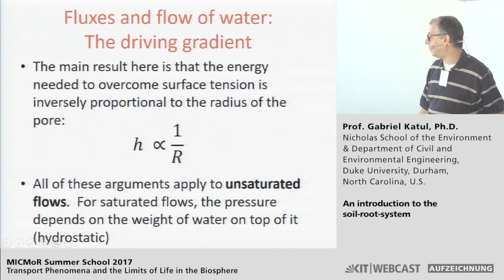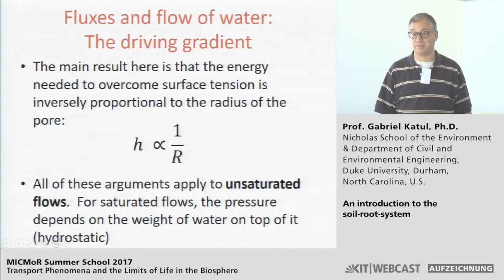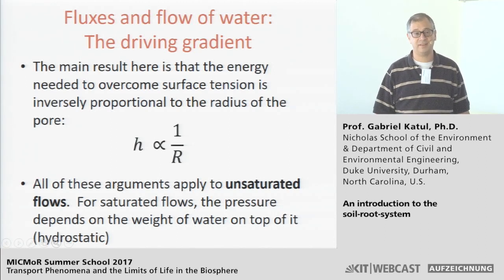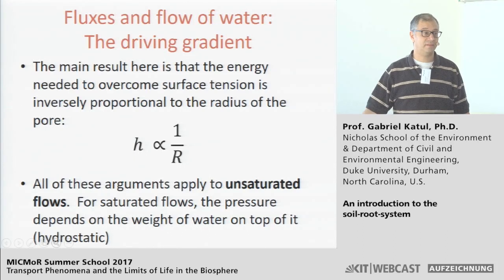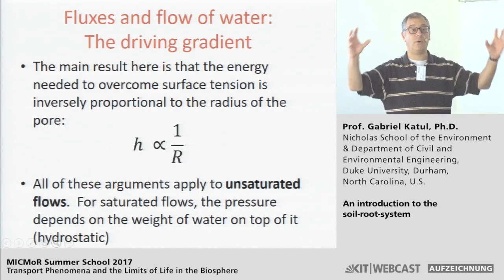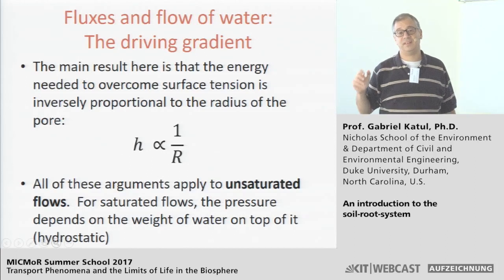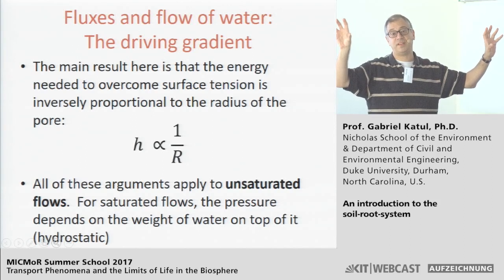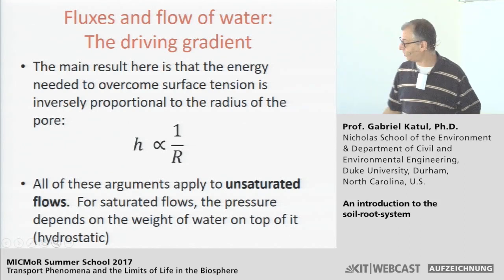But if the soil is saturated, then you don't have that problem, because basically you have almost positive pressure in the soil system, not negative pressure. Very much like hydrostatic pressure, like you jumping in a lake: as you go deeper, the weight of the water on top of you dictates the pressure. Similar arrangements happen if you are dealing with groundwater flow, which is completely saturated. So if all the pores are connected and filled with water, then you basically experience the equivalent of hydrostatic pressure. But if you have a lot of gaps, you have to pull the water against the adhesion, or surface tension, to get the water out.